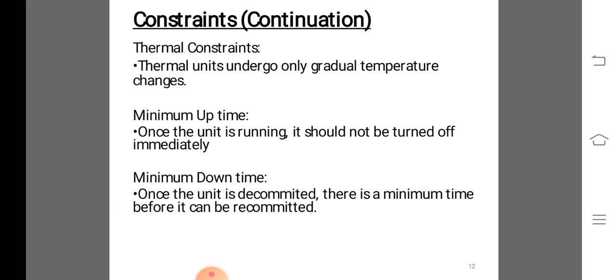Typical rules specify that reserve must be a given percentage of forecasted peak demand, or that reserve must be capable of making up the loss of the most heavily loaded unit in a given period of time. Others calculate reserve requirements as a function of the probability of not having sufficient generation to meet the load.